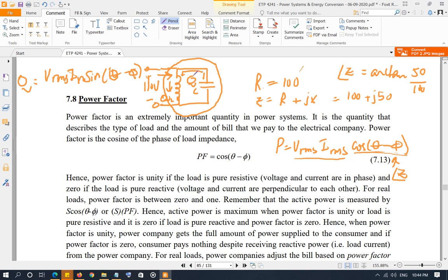Now, if the reactive power supplied by the capacitor is more than what is required by the inductor, then it will fully support the inductor, and the rest of the power is going to go back to the line actually. So the line current is just going to get even smaller in that case. All right, so this is the concept of power factor.